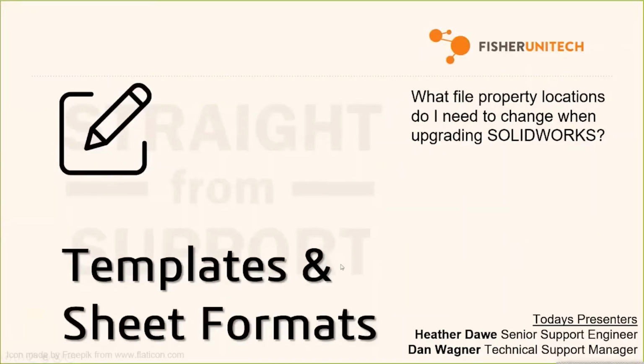The next thing I want to talk about is templates and formats, and this is one I see get skipped over a lot. A lot of people upgrade and they don't upgrade their templates and they don't upgrade their sheet formats. In tech support, we've gone back and seen people have sheet formats from 2008, and they're starting to get a little bit buggy, or they're just not working really well with SolidWorks because they're 10, 11-year-old sheet formats.